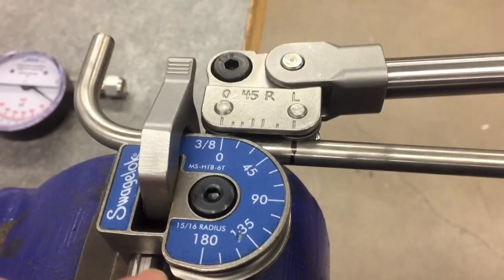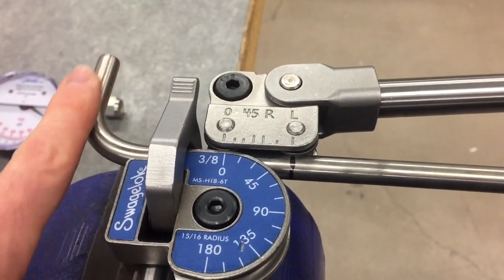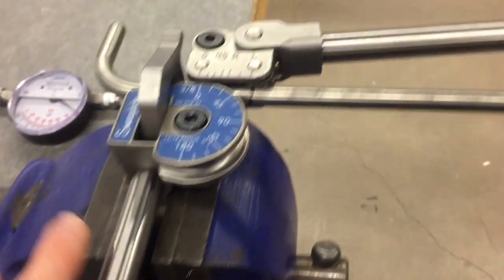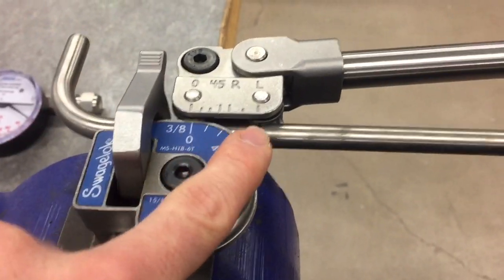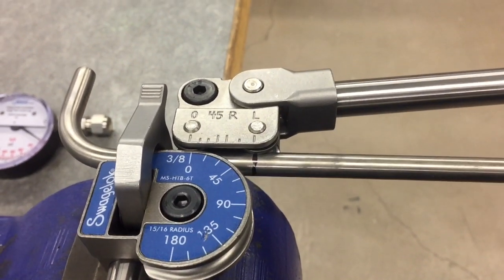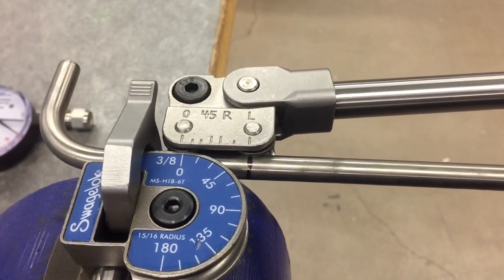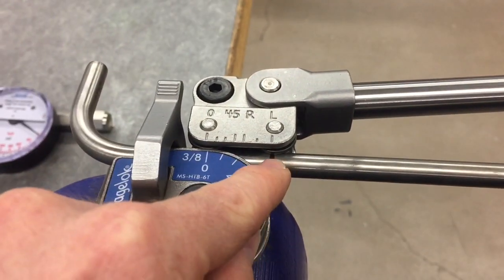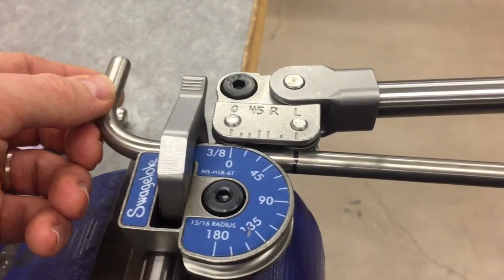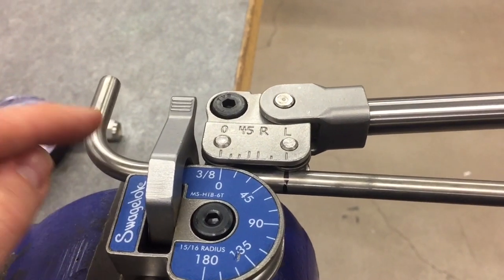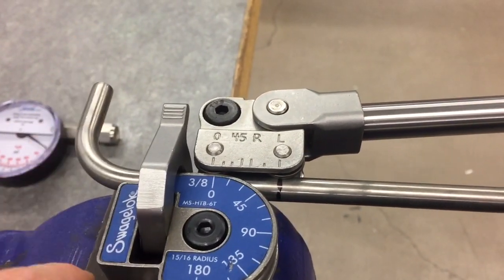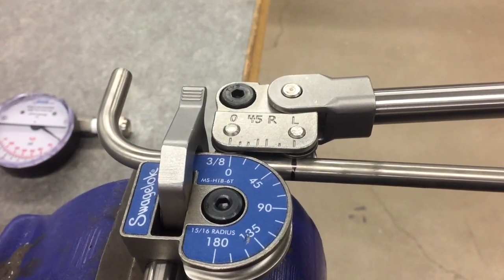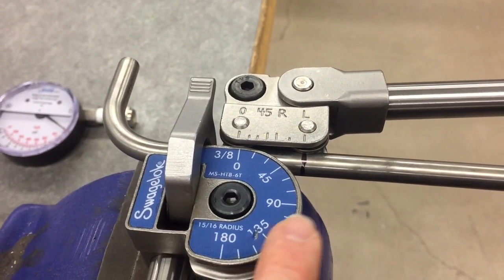But anyways, so I have this lined up. We want to make sure that this here is completely parallel with our bender arm here, right? So this bend gets made straight up. As long as this is lined up correctly and our bend is going to go the right way, because if we had this flipped the other way, then we'd be bending it straight back down. We don't want that. We want to bend it so it comes up into the bottom of our 5-valve manifold. So now I'll go ahead and make this bend.